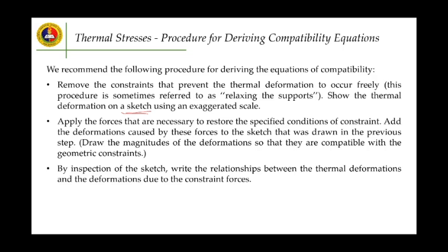However, if there are restrictions, then in our compatibility we will include the elongation which relates to the possible internal force that will manifest inside our material. So basically, it is a combination of these two formulas. Elongation is equal to alpha L times the change in T, and also elongation is equal to PL over AE, which is equal to stress L over E.